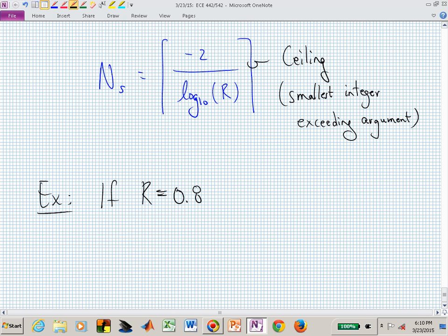Suppose somebody finds their dominant poles and they see the radius, or the magnitude, of those complex poles in the z-plane is 0.8. And those are the biggest magnitude poles that you have in your system. So we'll just agree that that's going to dominate. If they're all lumped together, they're going to kind of sing together and help with the damping. But we'll just pick the biggest one and say that's what we agree to.